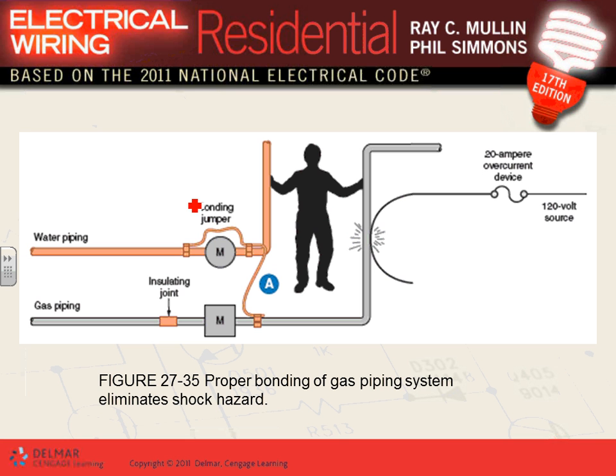Bonding, guys. Here's a good example of bonding. You have a water pipe, you have a gas pipe above ground. Gas pipe above ground, typically we bond them to that water. So why do we bond them to the water? Because if you have an accidental contact between a hot and the gas pipe, could it happen?